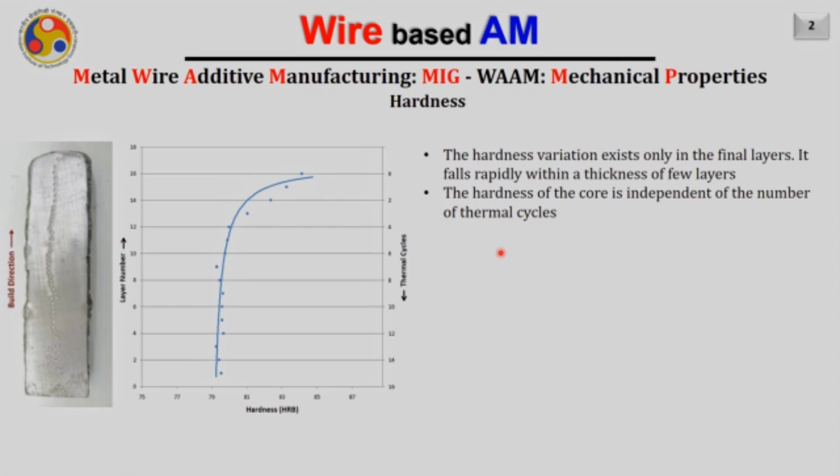However, most of the geometric parameters are dictated by the multi-bead and the single bead deposition only. Once you understand the shape of the single bead, and the optimal overlap in the XY plane, or if you are building one bead over another, what will be the height of the bead deposited on the curved beads, then that is sufficient information to maintain consistent mechanical and metallurgical properties.